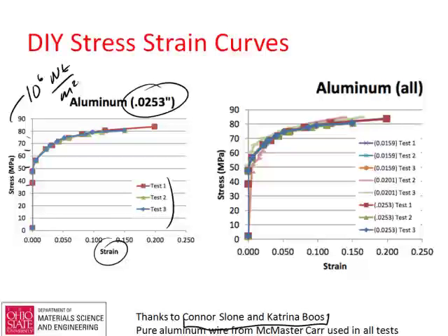And then they could also look at different wire diameters. These are the 3 tests that you see over here. Then here's a smaller diameter wire, and here's a smaller diameter wire yet. What's really interesting is these take a much smaller force because the diameter is not quite half, but the cross-sectional area is probably about half.